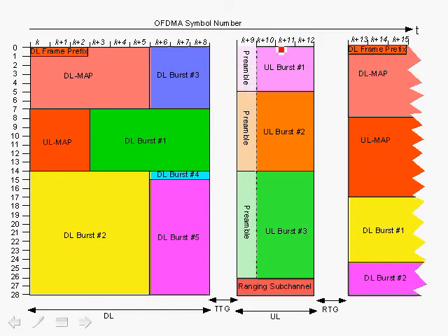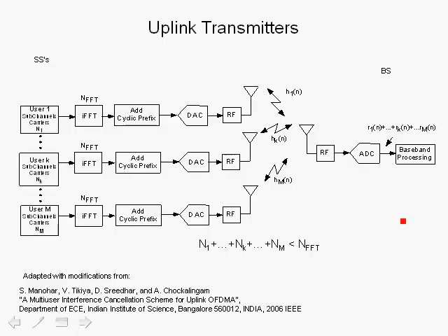One thing to notice is during the uplink, every uplink from a particular user has its own associated preamble, so that the base station can do acquisition on the preamble for, for example, burst number 1, and equalize the channel associated with burst number 1, which will be a different type of multipath environment than in burst number 2. If we go down here, we see that each user has a different multipath environment depending on where they are in the network.